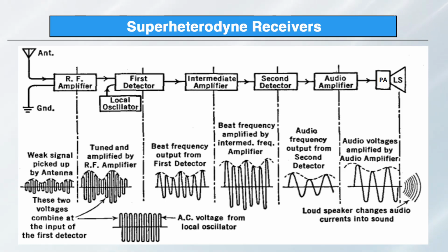The characteristic of this component is that it operates in the audio frequency range of 20 Hz to 20 kHz with a linear response to faithfully reproduce the audio signal, and may consist of one or more stages of amplification to achieve the desired output level. The design considerations: it must ensure low distortion and high fidelity to accurately reproduce the original audio signal. Impedance matching with the output transducer, speaker or headphone, is crucial for efficient power transfer.